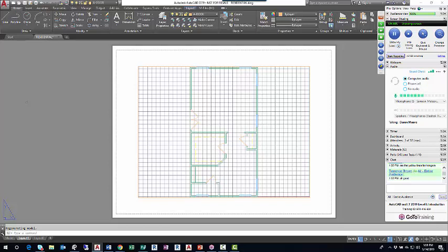They're all kind of the same thing. When you switch from model space to layout space the very first time, the window that I can see my drawing through gets created on the current layer. So if I hover over this window, which is called a viewport, it tells me it's on the layer A door. So that just got created. It's showing my drawing perfectly centered, which is fine, but it won't always do that. What will usually happen is AutoCAD will try to show you everything in model space without regard to scale. And it just so happens this is the only thing in my model space, the floor plan.